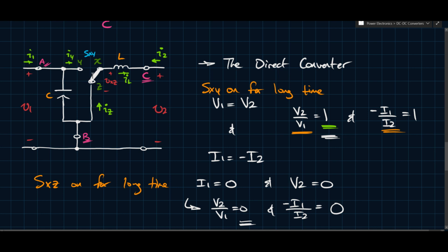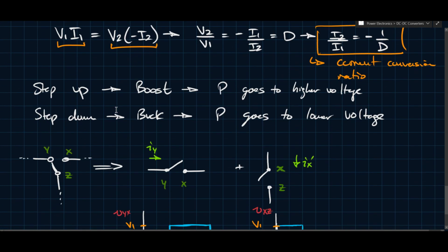Now, on the other hand, in the shunt element, so this XZ switch, the current and the voltage are going to be opposite. So the voltage you'll see is defined this way, but the current is going to go up this way. And if you remember in the video where we conceptualized the converter, we saw that the current was a minus current that was going up, remember, because we had a smaller current here and we had a larger current here. So we required current to come up from this shunt branch. And so the only way you can have current and voltage in the opposite direction in any type of switch is if you have a diode. Well, in the simplest case.